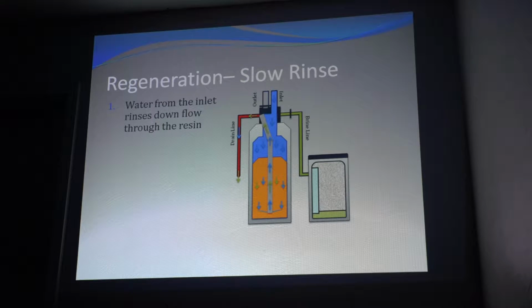When you use a twin, the unit regenerates with soft, iron-free water from the other tank. So you get a truly clean resin bed at the end of the regeneration. So when that unit comes back online, you're going to get good high-resolution, soft, iron-free water.